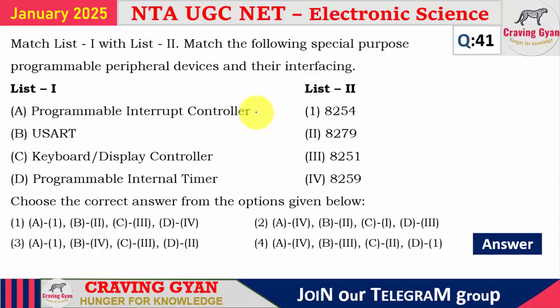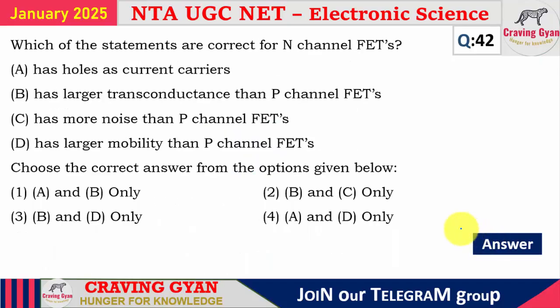Question number 41, match the following. Such a simple question they have asked. A programmable interrupt controller is 8259. Universal synchronous asynchronous receiver transmitter is 8251. Keyboard or display controller is 8279. Programmable interval timer is 8254. So based on this, if I am solving, which option is going to follow? Option 4 is correct.